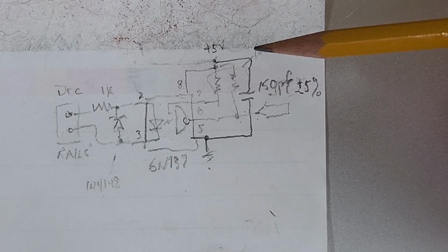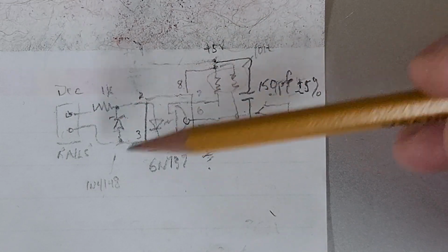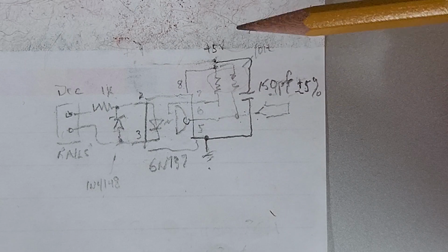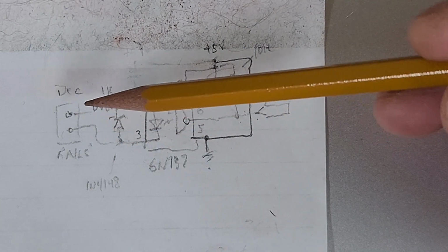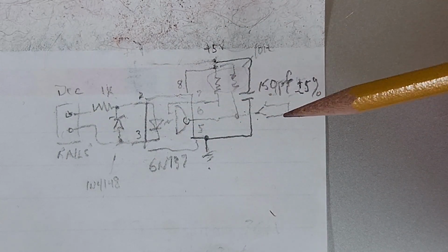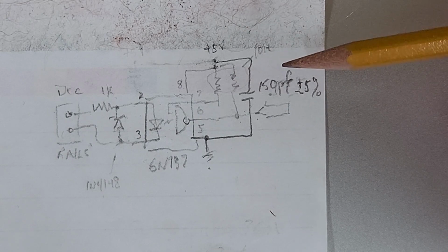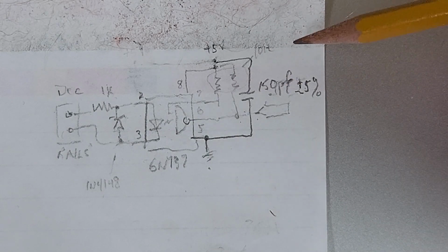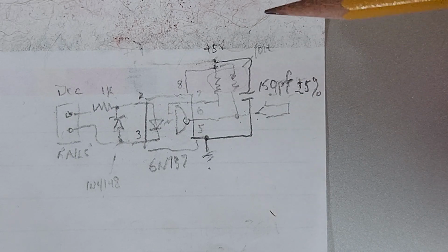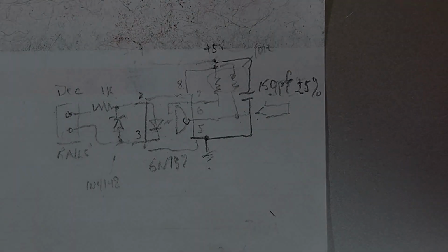So in this case, I don't care about converting this to a DC. What I do care about is converting the AC square wave to a series of pulses that I can convert back into packets of DCC commands, and then transmit those DCC commands back up to the PC application. I'll show you that, and I'll show you the signals.